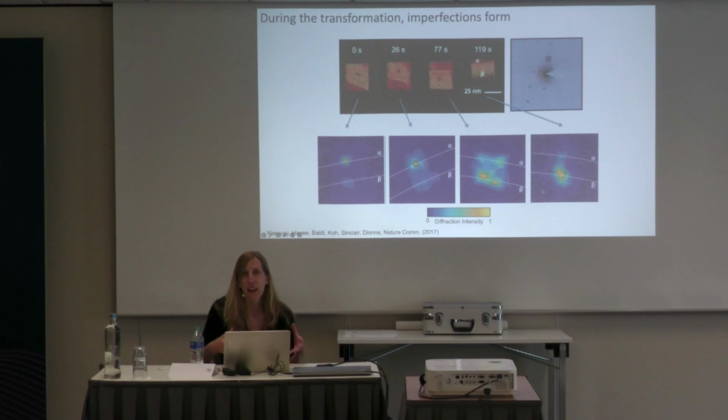There are lattice imperfections forming when you have coexistence of alpha and beta, right? Your lattice is strained where the hydrogen is going in, and that's giving rise to various imperfections that are giving rise to this more spread out diffraction pattern. Here, just to be clear, we're zooming in to that one diffraction peak, but you could zoom into any diffraction peak and see the same sort of behavior.